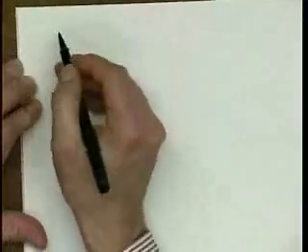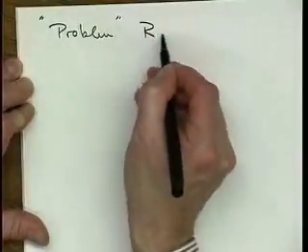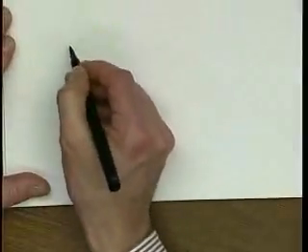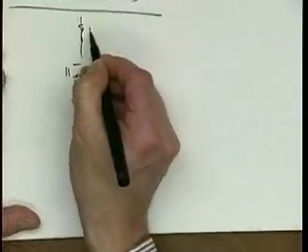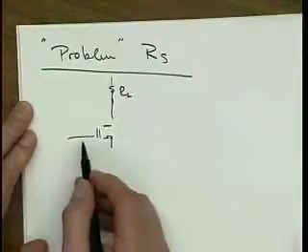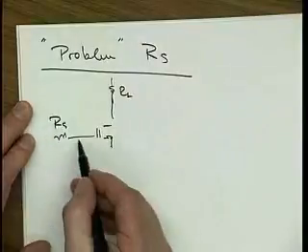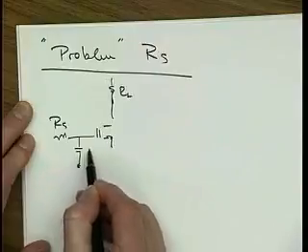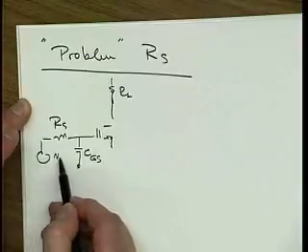Now, there is one further little problem with input-referred noise sources, and that's RS. Let's modify our common source example one more time, just a little bit. We have again RL, and now I make my RS here, and I drive it with a voltage source, VI.